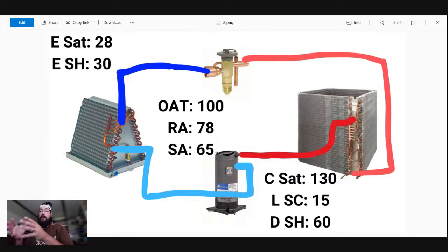So a couple of options. All right. On a high level, when we see this, some of the first thoughts we might have is, okay, what's our charge, right? So one of the big go-tos we have when we see a system not keeping up, customers complaining, is do we have a low charge situation? So we can work through that as the first example.